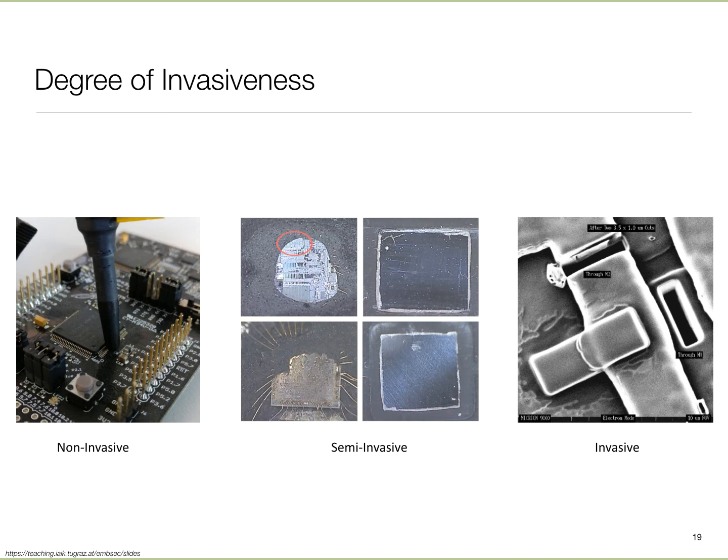There is also work where you remove the cover of a chip and then you put a high resolution thermal camera on it, and that thermal camera tells you how much heat different parts of the chip are producing. And now you begin to get a map of which transistors are more active, which are less active, and you reverse engineer those. So rich set of things.